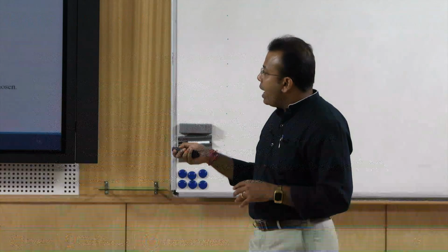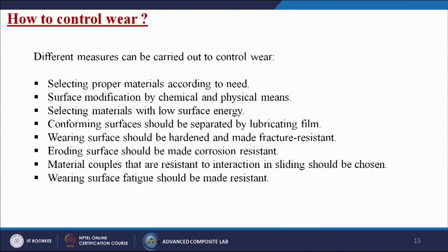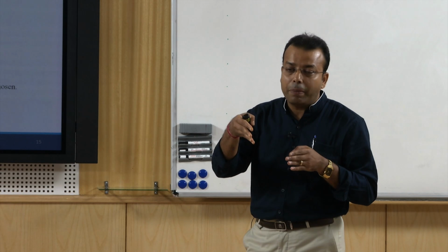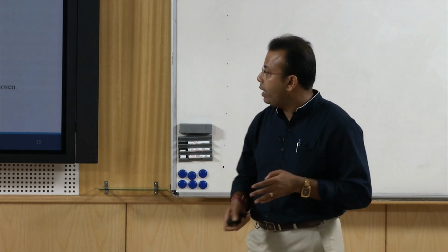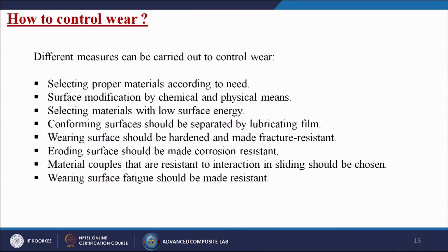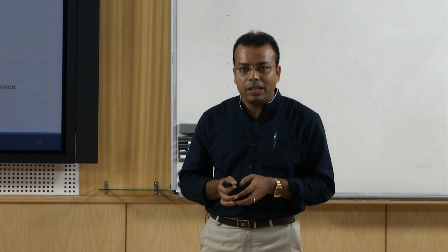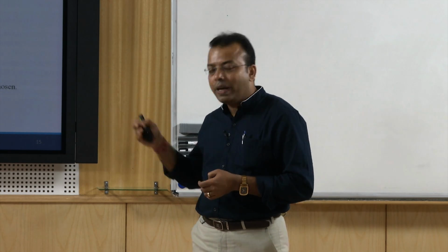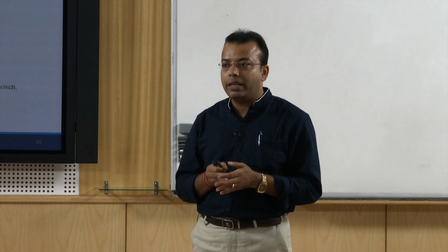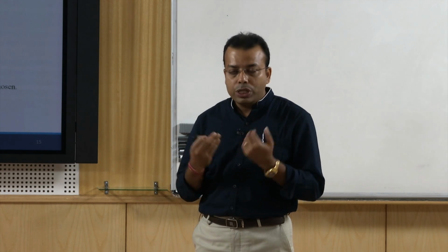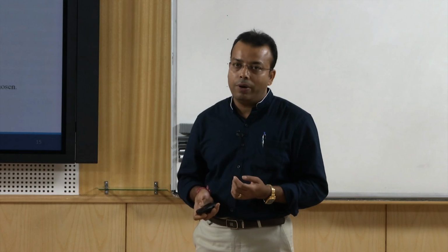The wearing surface should be hardened and made fracture resistant, so that there will not be any cracks or pores through which water molecules or chemicals can go inside the material. Material couples that are resistant to interactions in sliding should be chosen. Wearing surface fatigue should be made resistant. These are all remedies, and what I have explained here is the standard set, but there are n number of remedies which we can adopt to save our material.